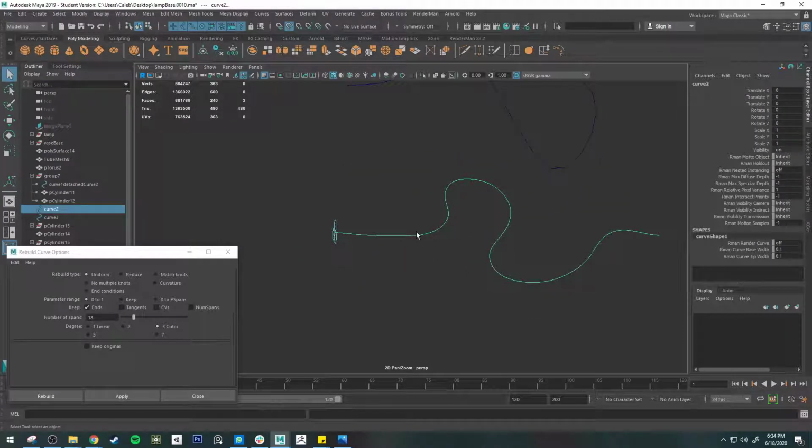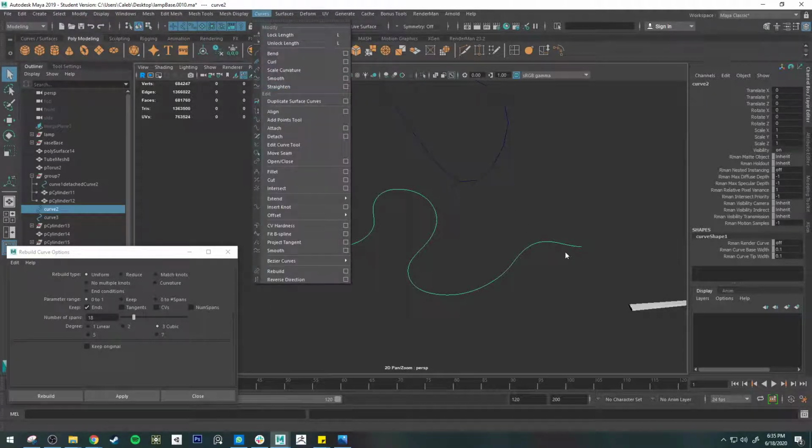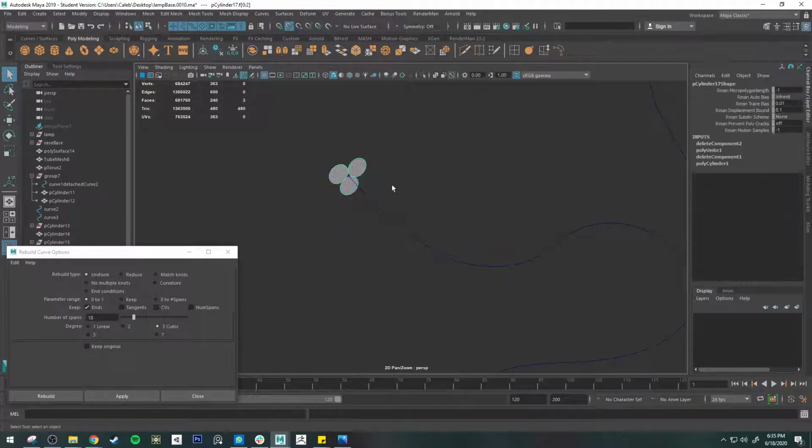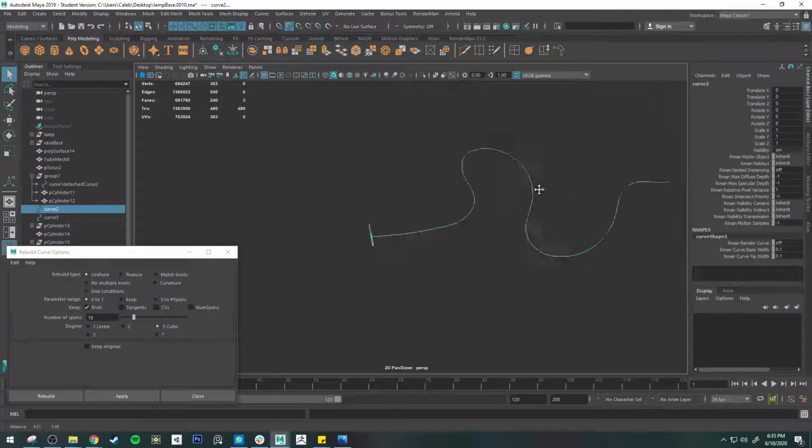sometimes you might draw your curve backwards, and so you'll notice a different problem. I didn't draw my curve backwards, or I knew where the beginning of my curve was, or the bottom. So what I'm going to do is reverse this curve really quickly just to show you what it would look like if it was reversed. Because you can't tell just by visually looking at it. You would have to know how you drew the curve. So what I do is grab this.